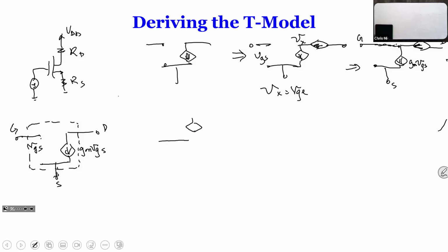We're going to move the current source to the right-hand side, instead of having them flat, and we just move them around to form that circuit. Now you see this circuit is identical to this circuit. We just changed the view, we didn't change the configuration of the circuit. Both currents are equal to gm times VGS.